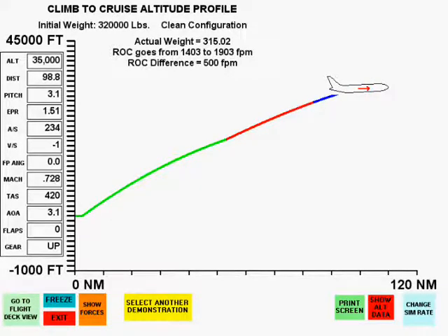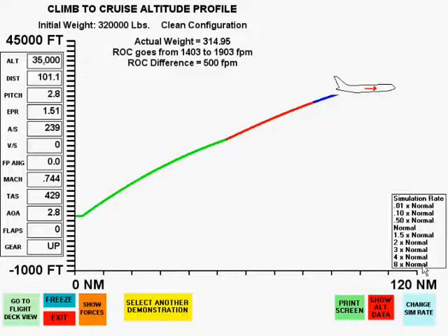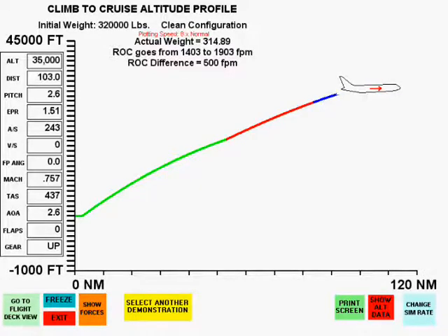We now know that the previous rate of climb curves are an oversimplification. A constant Mach climb has a different set of rate of climb curves, which are higher than those for the constant indicated airspeed climb. In reality, at the Mach intercept point, there is a jump from the constant airspeed climb curves to the constant Mach number curves.